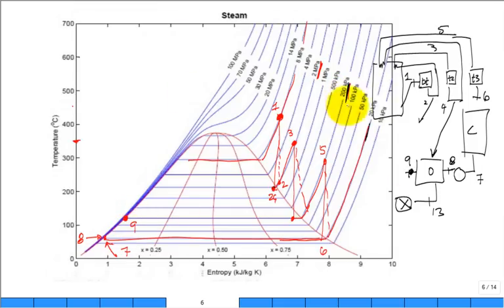Then we put it through another pump. And that's where I got a little ahead of myself, right? Now, where is state 10 after the pump? Sure, it's just like the relationship between 7 and 8, just like 9 and 10. So state 10 is right there. What's the pressure at state 10? You're going to feed a different type of Feedwater heater. What type of Feedwater heater was the first one? Open. The next one was closed.